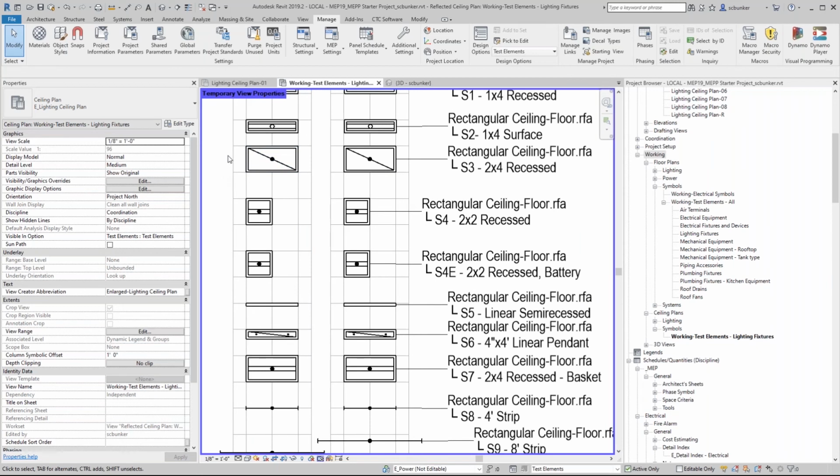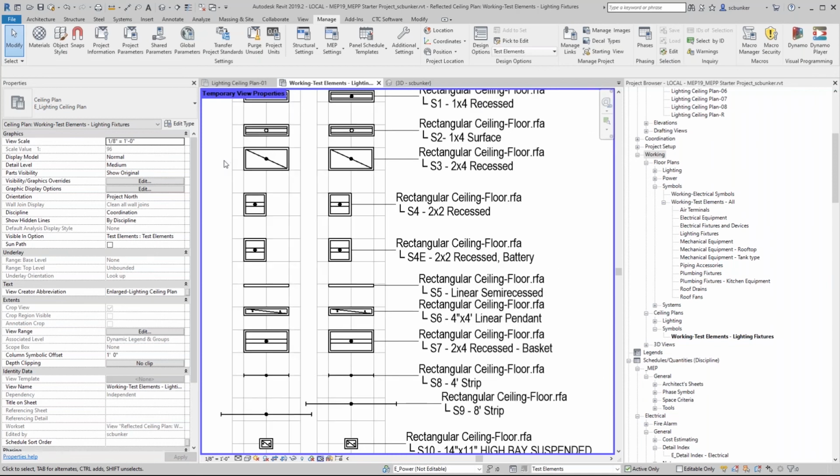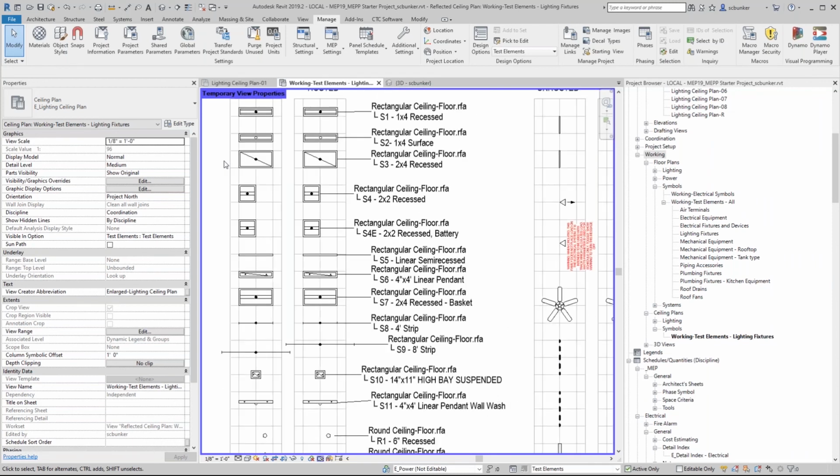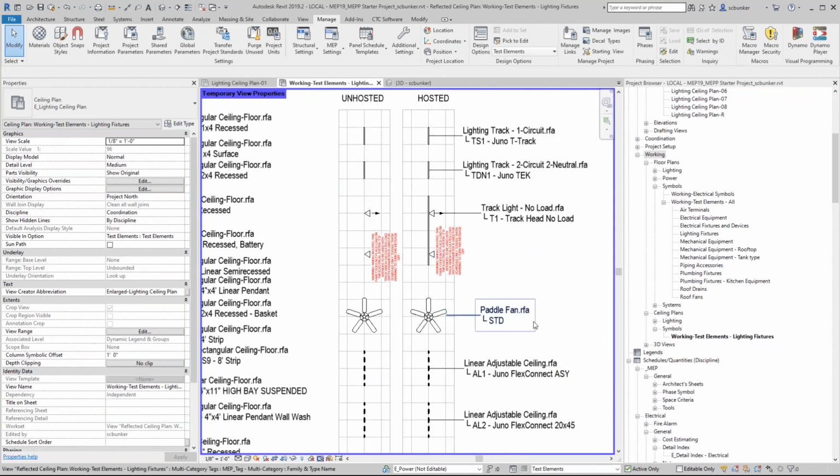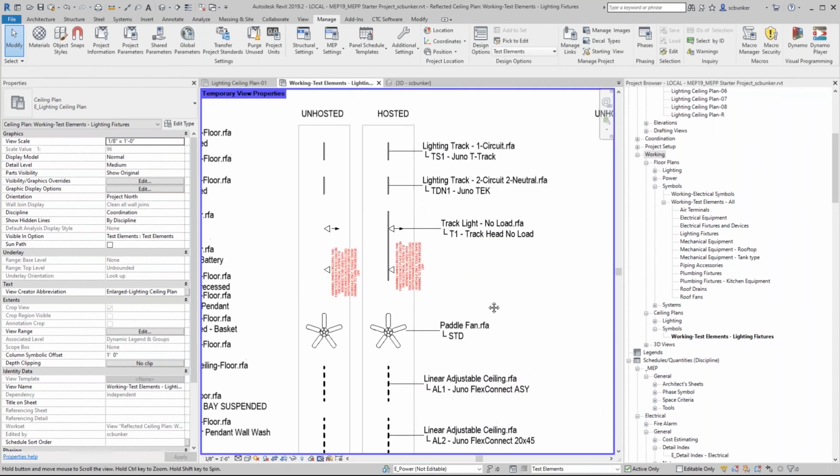And see, Revit can't handle ATS type functions natively, and so you have to use workarounds that have pros and cons. So hope that answers the question. If it doesn't, you can come back and I'll keep going.